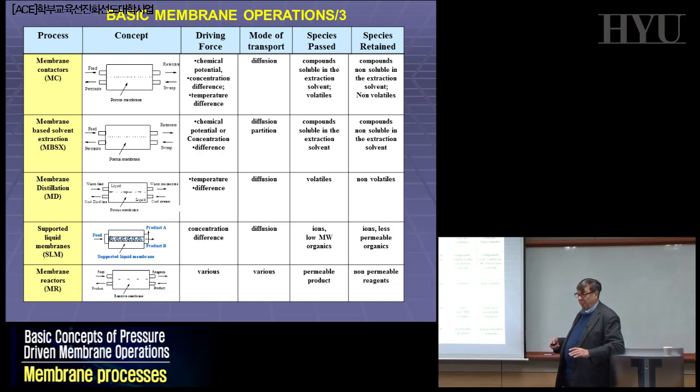dense at all, full of big pores, in which what is happening is creating an ideal contact between the liquid phase and the gas phase, and through the pores, in which only vapor can go, you will evaporate some molecules in the pore, and they will go across with a very small delta T as driving force. That's totally different from reverse osmosis.